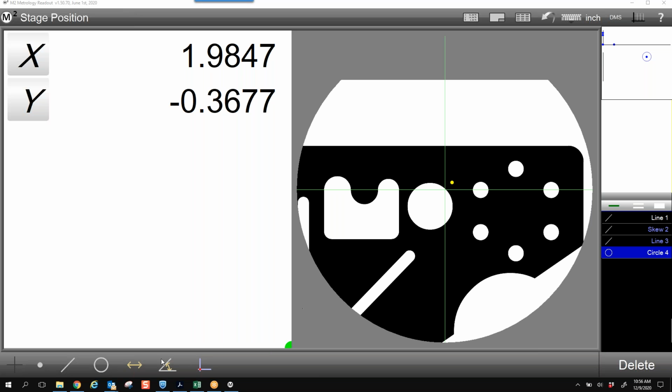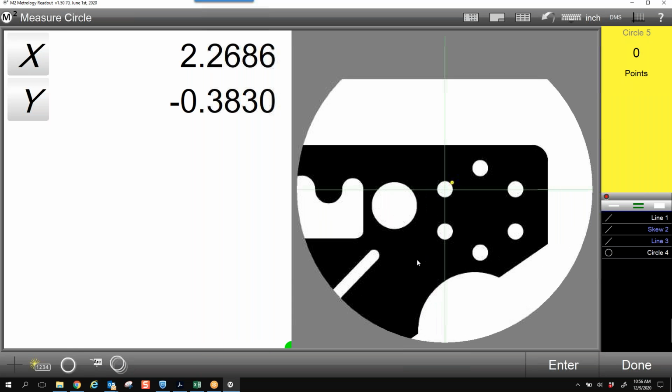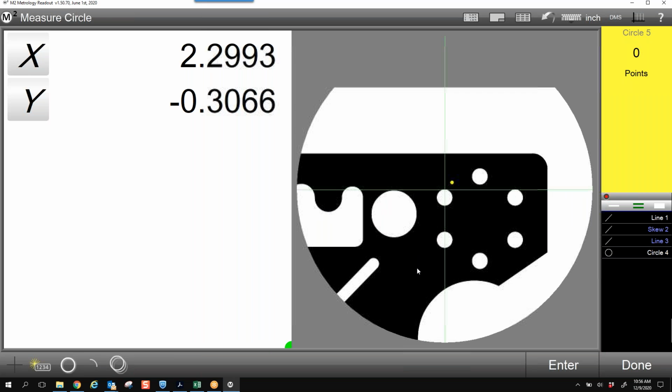Okay. So that's doing a circle that we did. Now, let me show you another way of doing a circle. We'll do this arc over here, okay? Or we'll do one of the circles in the bolt hole. When I hit circle, I'm going to come over and I'm just going to do points. And I can either click in this area or hit enter, either way.